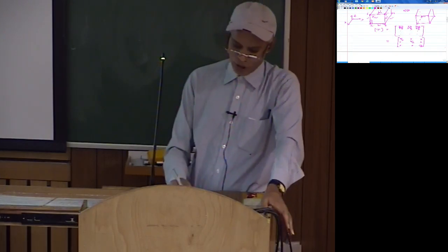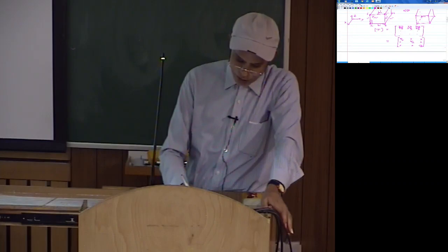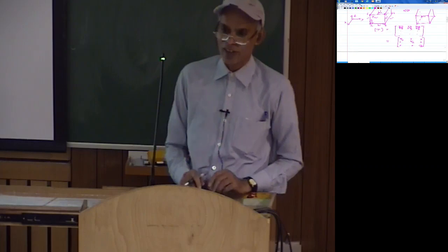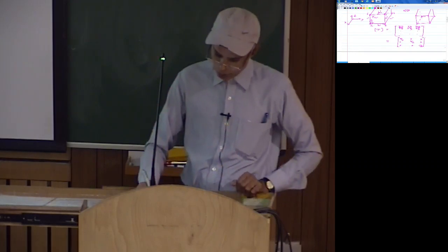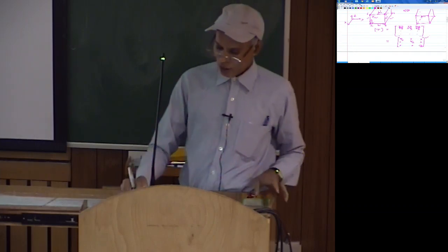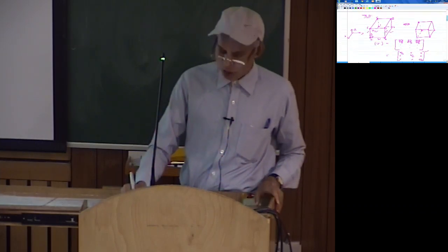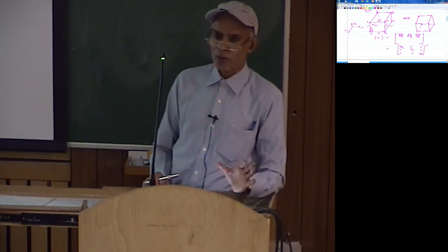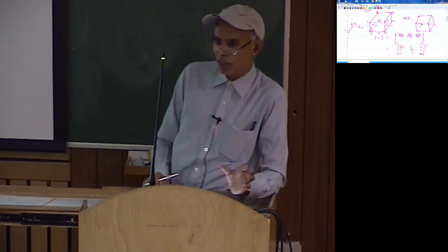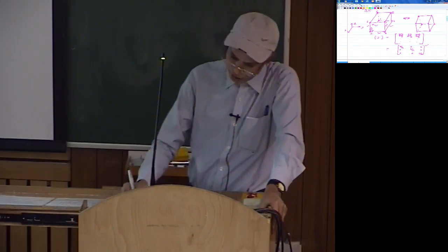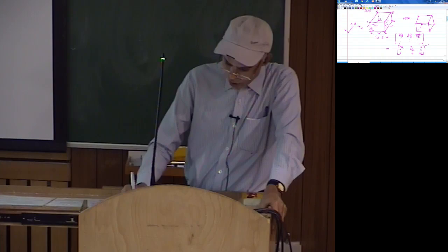In case the element is a cuboid, that is, all the included angles are 90 degrees, that is the ideal requirement, because in that case your Jacobian matrix is actually constant. Then if you are using a 2 by 2 by 2 integration rule, that will exactly integrate the stiffness matrix, provided the numerical truncation errors are taken care of and you use sufficient precision.